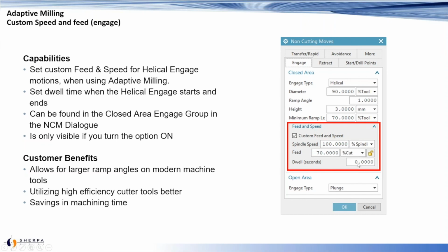You can even add a dwell, so when it gets down to the bottom, especially I've noticed with certain machines, when it's getting down there, especially if you have your speed and feed drastically reduced, sometimes your feeds can ramp up to speed faster than your spindle, and so this dwell allows your spindle to catch up a bit before it just starts feeding into the part.